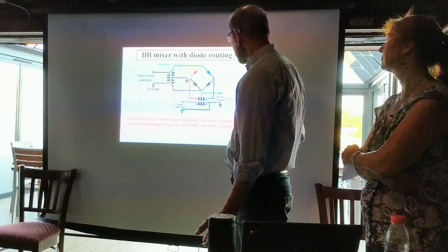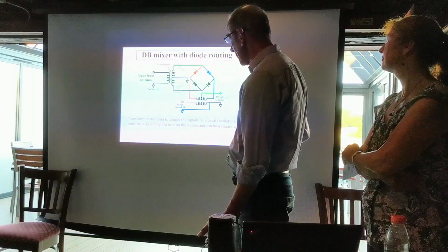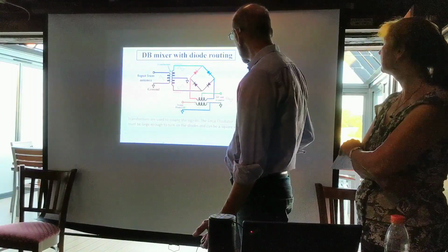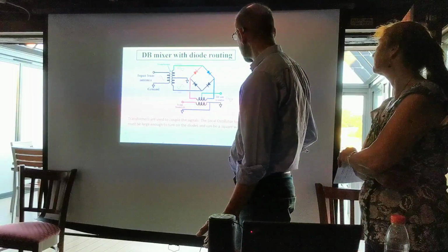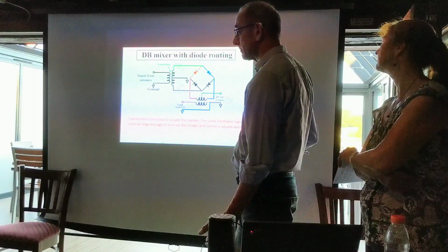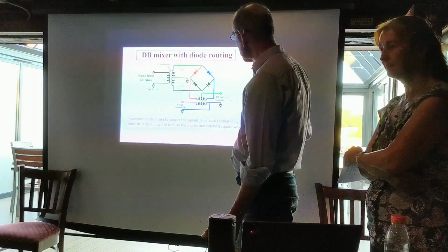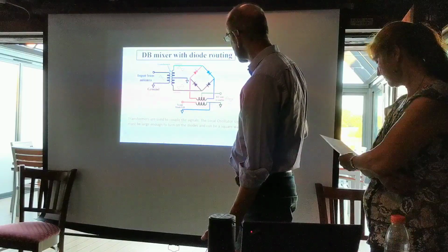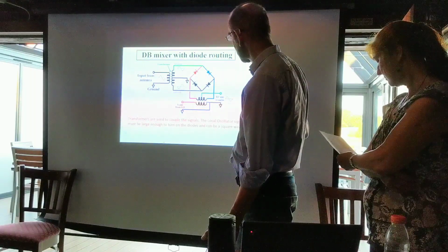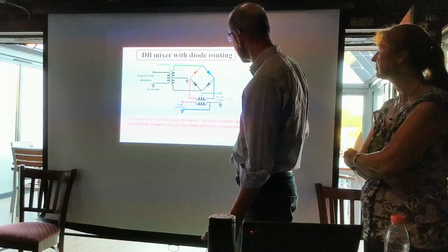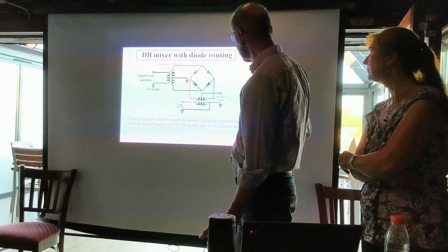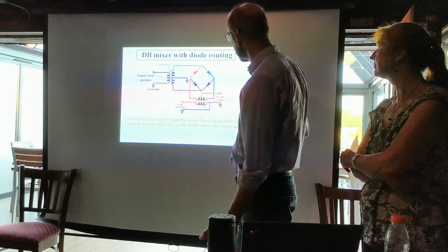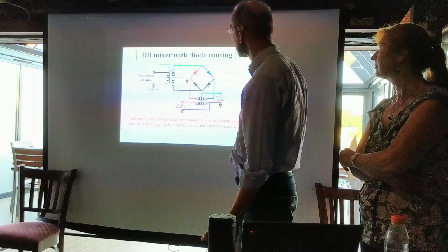Now, let's take the case where the square wave is on its positive part, its positive phase. Then we will have a plus here and a minus here, and that will be reflected on the secondary of the transformer. Now this plus will then appear on this diode, and a diode conducts when its anode is more positive than its cathode, and in this case you can see it is. This is the negative end, and the cathode, you can see this diode is negative, and the two diodes are in series, so they both conduct.